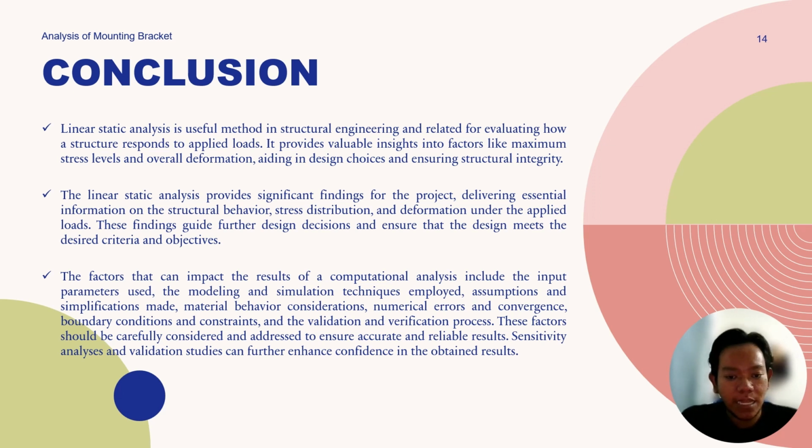And the factors that can impact the result are the input parameters used, the modeling and simulation technique employed, assumptions and simplifications made, material behavior considerations, numerical error and convergence, boundary condition, and last but not least, constraint. These factors should be carefully considered and addressed to ensure accurate and reliable results. Sensitivity analysis and validation studies can further enhance confidence in obtaining the best result.